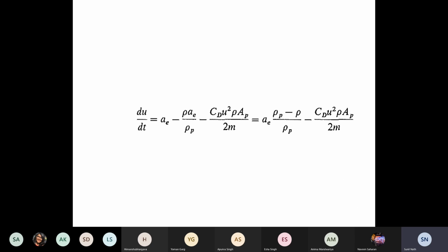And imagine we are still doing free settling, and we only have single particles. As I said, there's no exact solution the moment the settling becomes hindered. But one thing we know is that the presence of other particles, as we would expect in a bed of solids or in a filtration application, means the terminal condition velocity which you're going to derive for the free settling case is always going to decrease. The factor depends on the situation, on the bed and the porosity and so on. Anyway, first let us get this general result.